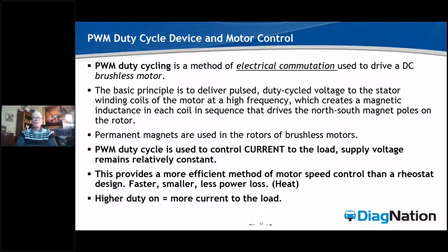Why? Well, we're conserving the wear on that motor by pulse width modulating it based on what the engine needs for fuel pressure runtime, versus the old school where we'd flip a switch, a relay would come on, and you've got 100% power to that pump the entire time the key cycle's on in that car.